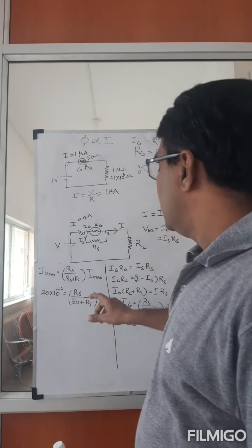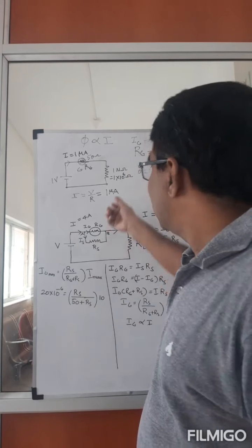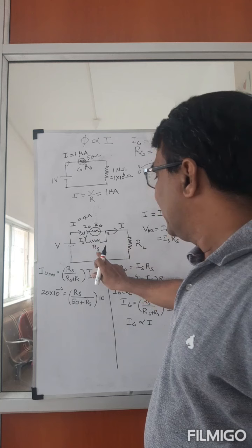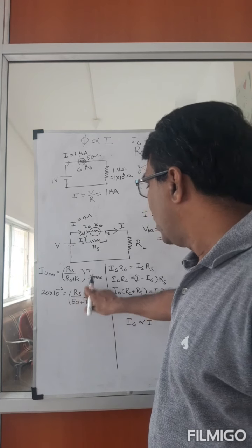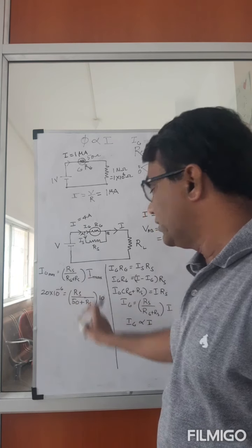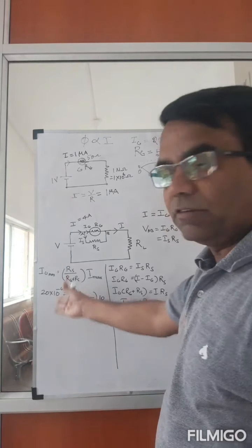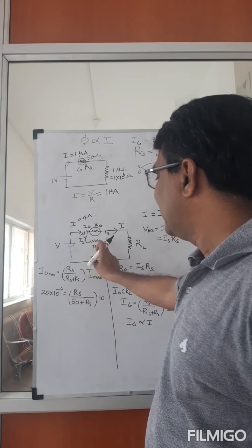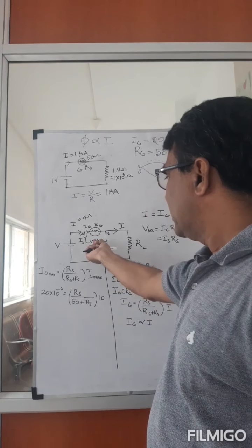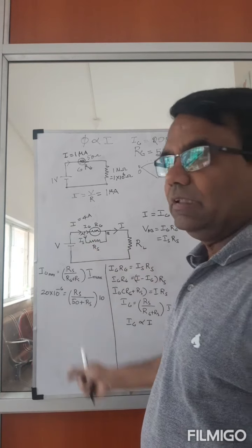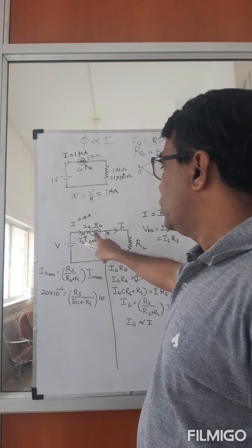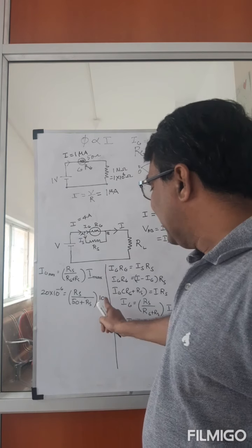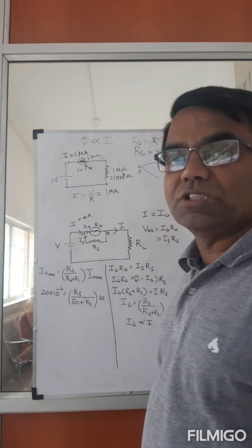What it means now is that I take the same galvanometer, which can allow only 20 microamps, and connect this value of RS, which I figure out from this. I'm not going to do it now, but you can figure it out yourself. If you take that resistance and connect it across the galvanometer, the galvanometer will show full scale deflection when 10 amperes is flowing through the circuit.